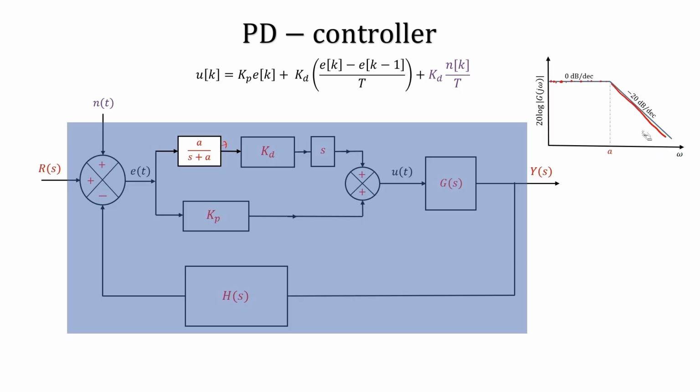By magnitude of the output, I mean the magnitude of the transfer function, and this magnitude will affect the input that is coming in. So, at higher frequencies the magnitude of the transfer function is very small, which means that this small number will multiply with the magnitude of the input, and the input will also get attenuated.